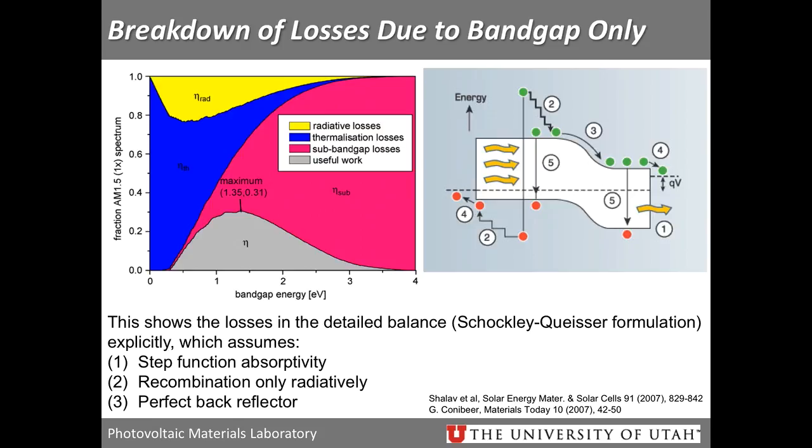And so when you're absorbing light that has an energy much higher than the band gap, the carriers are going to relax down to the bottom of the conduction band just naturally. And so where does the rest of that go? That energy goes to heating up the solar cell. So you have phonons that are generated as they relax down and bond vibrations that will heat up the solar cell. So as you can see, this blue is more of a problem at lower band gaps, which makes sense because a larger portion of your spectrum has energy much larger than the band gap.